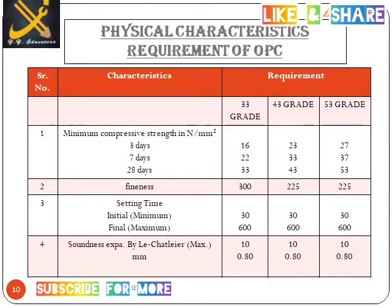Now look at 53 grade cement. Within 3 days it achieves 27 Newton per mm square compressive strength. Within 7 days it will achieve 37 Newton per mm square, and in 28 days it will achieve 53 Newton per mm square. This is the minimum compressive strength within 3 days, 7 days and 28 days.